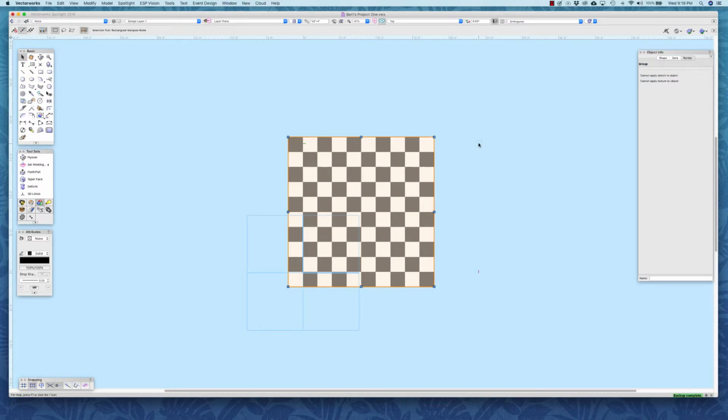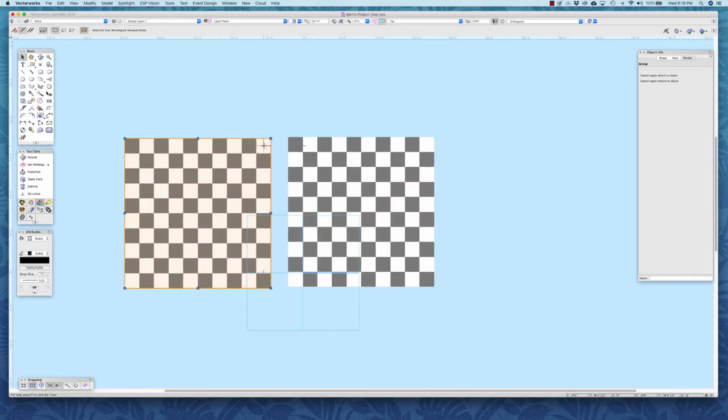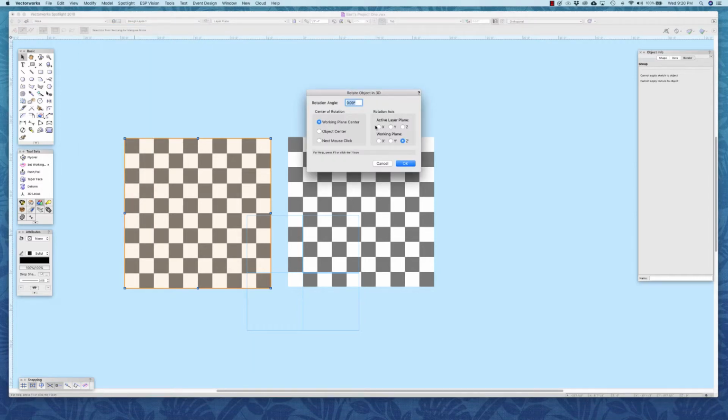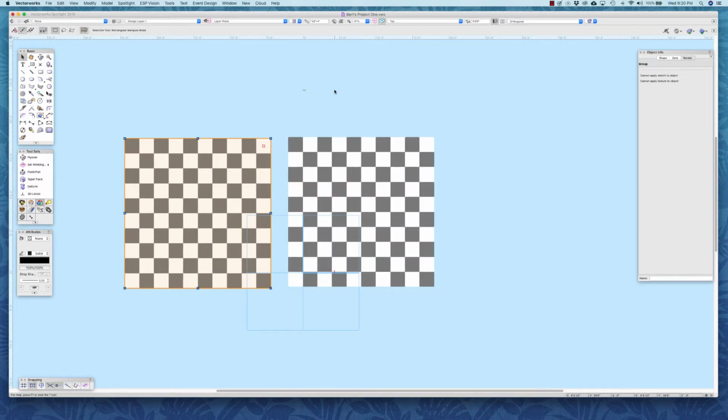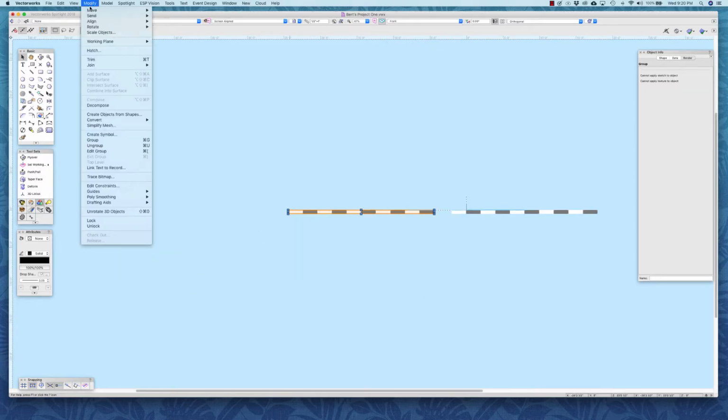Since the walls in our model are identical to the floor, we can simply duplicate the floor, move it to the side, and use it as a wall. However, we need to rotate the wall so it's vertical. There is a 3D rotation tool, and that might be the way to go for some of you, but I think it's easier to just switch to front view and rotate the wall to the right.